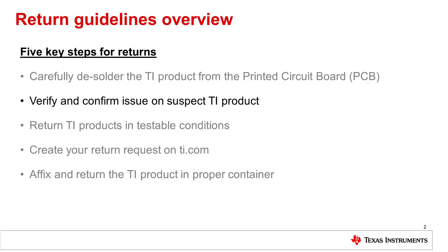In this video, we will guide you in the first step of your verification process, if you suspect an issue with a TI product. In the following, we will learn about the ABA swap, which is a great board-level troubleshooting technique. And in addition, it will help TI to understand your concern with a suspect TI product, separate from any application issue you may experience. This enables an efficient and effective quality review.